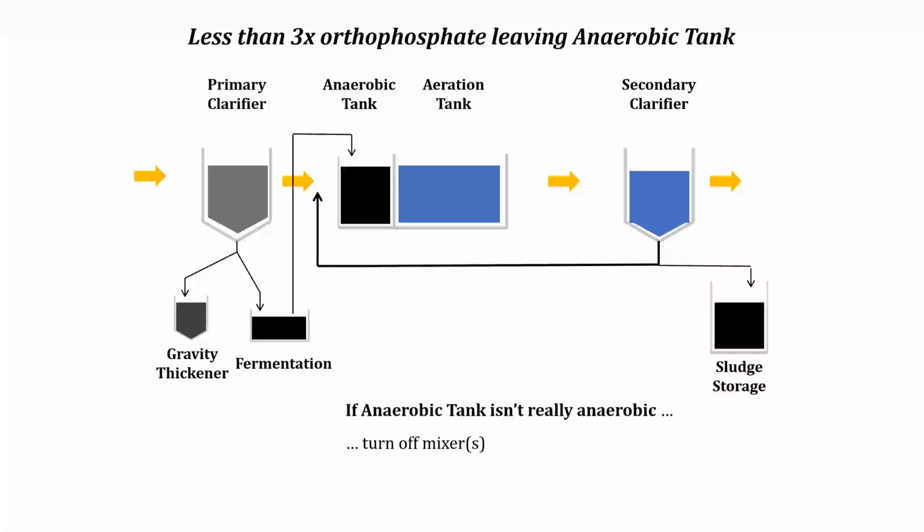Turn the mixers on again once a day to resuspend, or if you need to do it more often because you see a big drop in your aeration tank mix liquor, obviously you need to turn them on. But the example that I gave when I talked about the case studies of Great Bend turns their mixers on for 15 minutes a day. Otherwise, the solids sit there. And as they sit there, creates a stronger zone for that VFA production, a stronger zone for the PAOs, the bio-P bugs, the phosphorus accumulating organisms that are in the return sludge to settle down into that sludge and become energized from the volatile fatty acids.